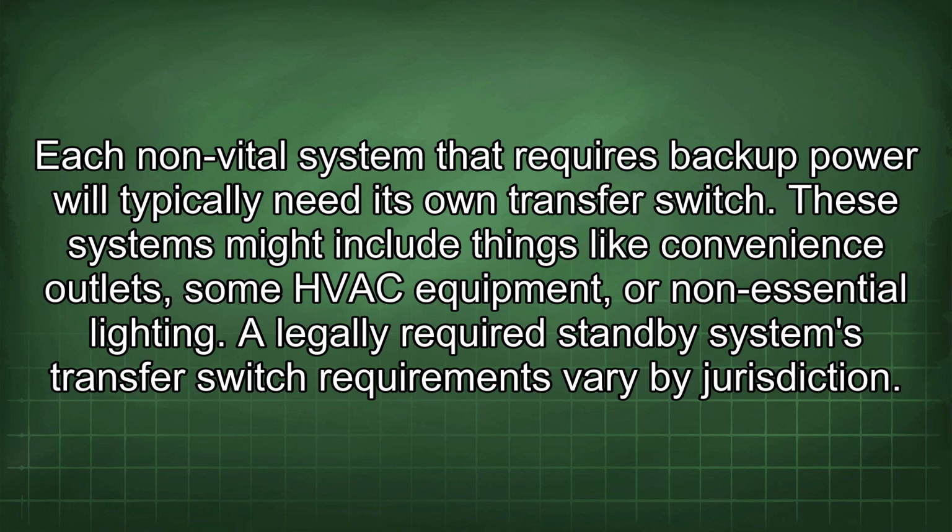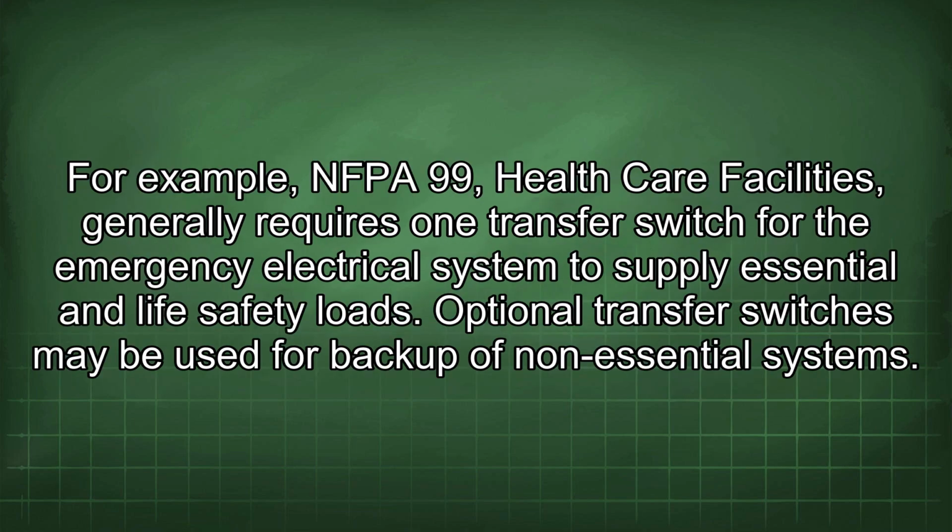A legally required standby system's transfer switch requirements vary by jurisdiction. For example, NFPA 99 healthcare facilities generally requires one transfer switch for the emergency electrical system to supply essential and life safety loads. Optional transfer switches may be used for backup of non-essential systems.